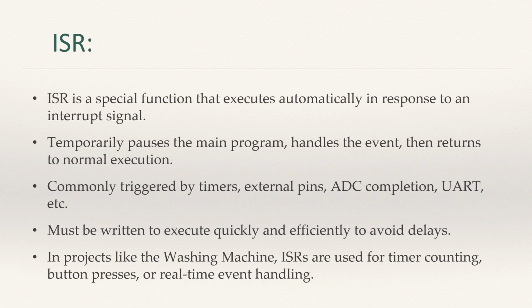ISR. An ISR is a special function that executes automatically in response to an interrupt signal. It temporarily pauses the main program, handles the event, then returns to normal execution. It is commonly triggered by timers, external pins, ADC completion, UART, etc. It must be written to execute quickly and efficiently to avoid delays. In projects like the washing machine, ISRs are used for timing, counting, button presses, or real-time event handling.